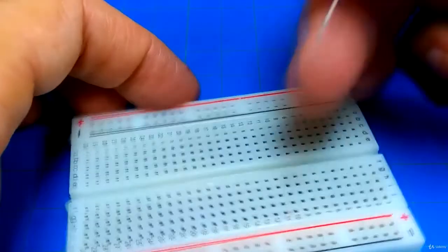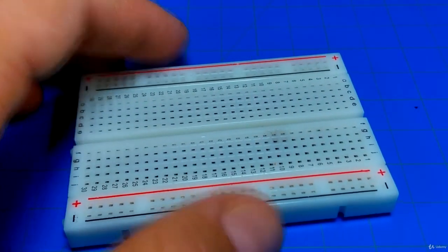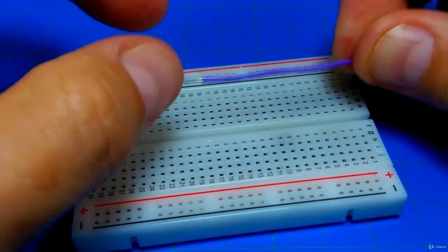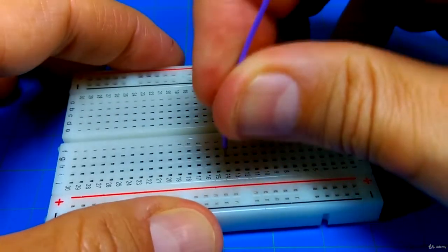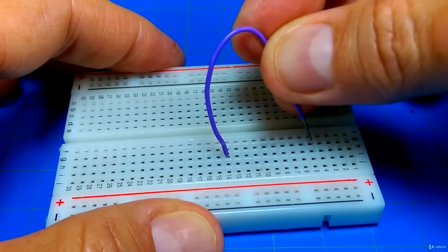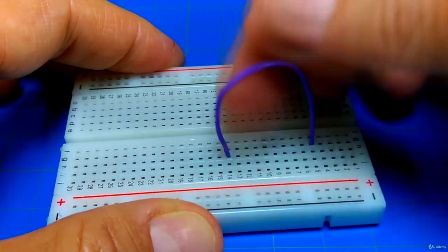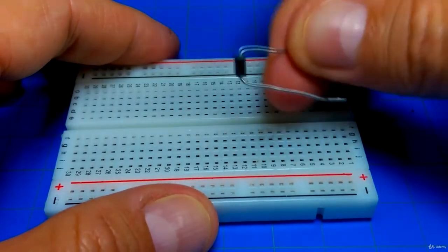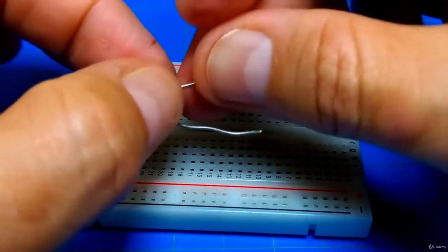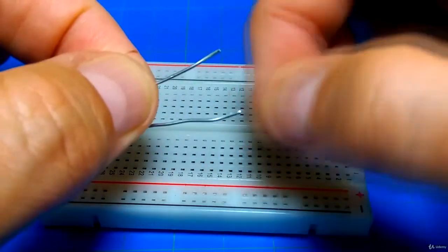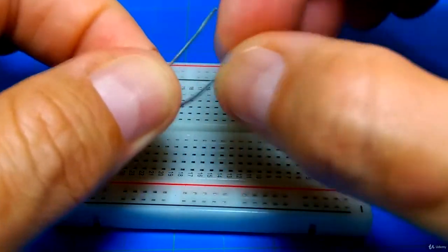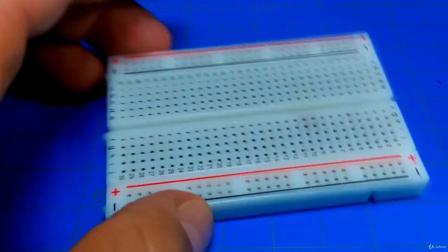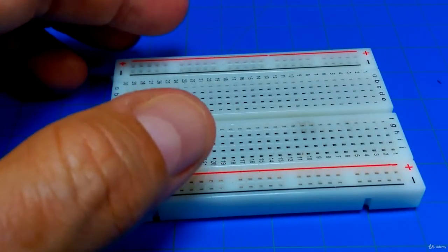Because when we're building things, we're going to take wires, and let's find a little wire here to show you. We're going to plug these wires into this board and connect things, right? So say we wanted to connect those two points. That went in really easily, right? But if I open these things up by putting in parts that don't fit, then I'm going to damage this board over time. So if you want to put these in here, you're going to have to chamfer these and get a little file. A little nail file works really well, or a little bit of sandpaper, and just put it down and go like that, go like that, all right? Real world stuff. But we're going to get to that more later.